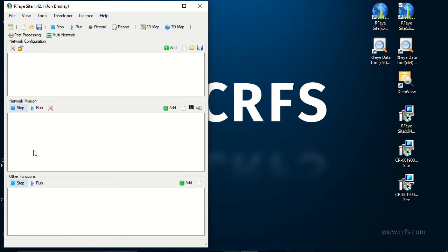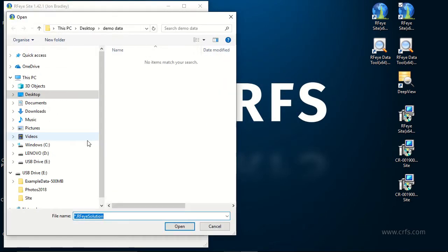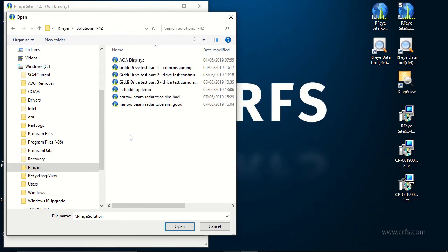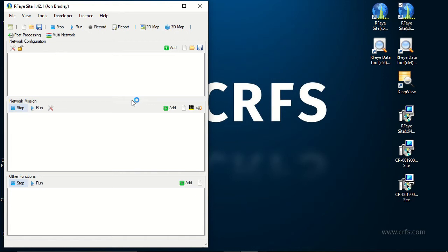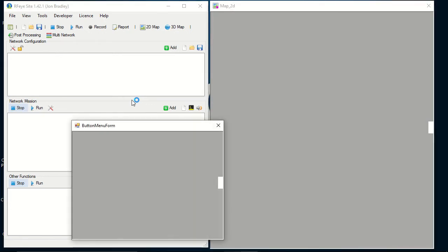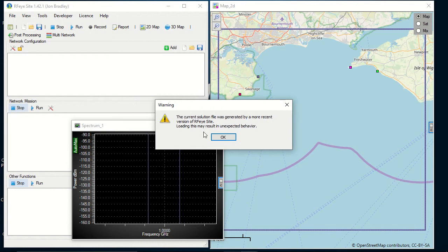So just a quick example of how TDoA techniques can be used even in some of the most challenging conditions, looking for transmitters with very narrow beam width. Often with TDoA, we're assuming that we're looking for a signal which is being transmitted out, and it's illuminating all of our receivers at the same time. So TDoA is synchronously hunting for a signal type, correlating the data, and then deriving back to the location.